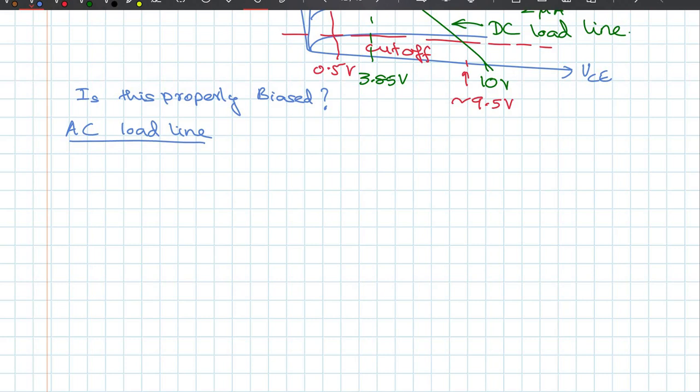So when you are choosing these capacitors, you have to choose them in such a way that at the lowest frequency of the input signal, these capacitors act as very low impedances or short circuits compared to the other elements in your circuit. Say for example, you have a resistor in the emitter circuit, RE2, which is 20 kilo ohms, bypassed by a capacitor.